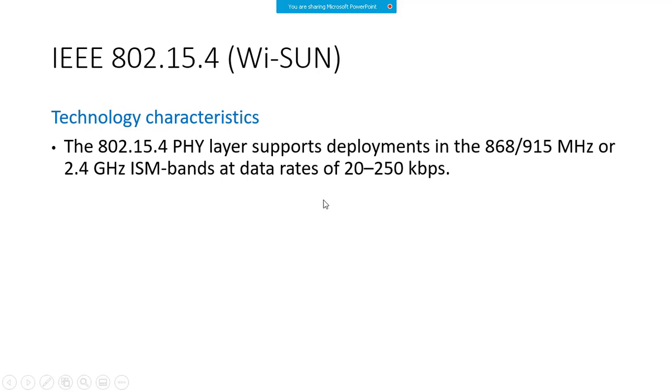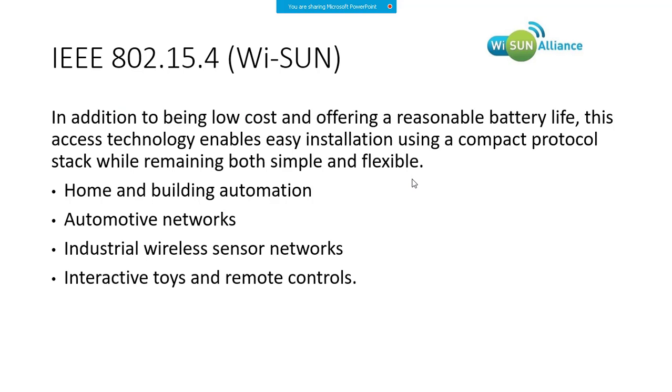And you can see the data rate. It is in terms of kbps. So I already said the objective of 802.15.4 is not to allow you to transfer files on the internet. It is for machine-to-machine communication. It is contributing in the IoT spectrum, right?